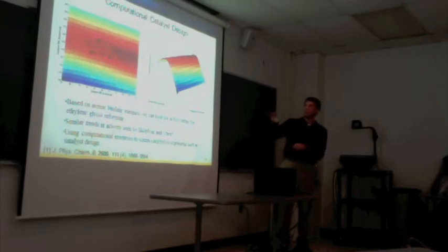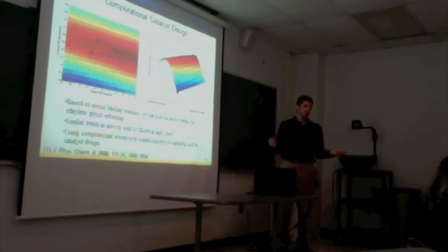Basically, if you remember, these are expensive metals, so we want to use as little as possible and get the highest surface area. To increase the surface area, we spread it out as thin as possible, because we're really only using the top layer. Anything that's not on the top layer is pretty much being wasted. So the thinner we can make these, the better off it is for our bottom line. If we can make one 10 layers thick versus 20 layers thick, we're saving half our money on catalyst expense.